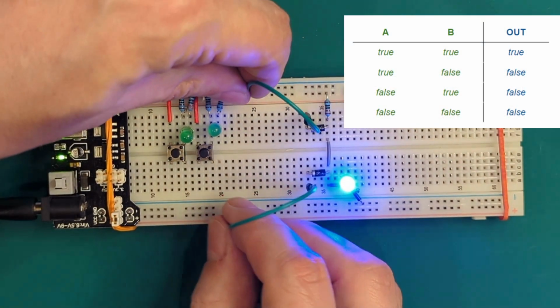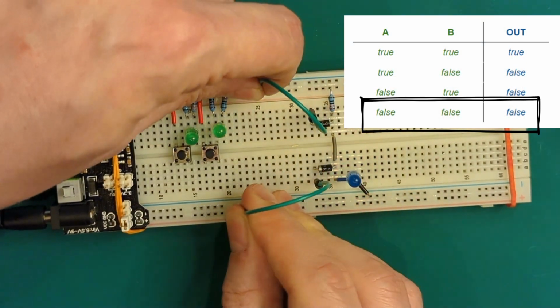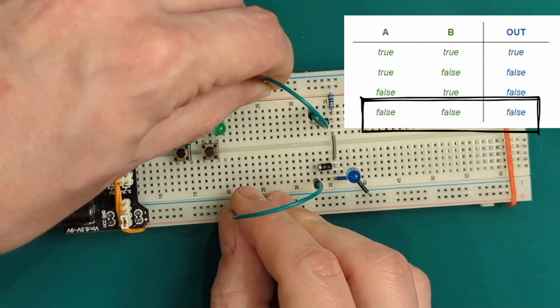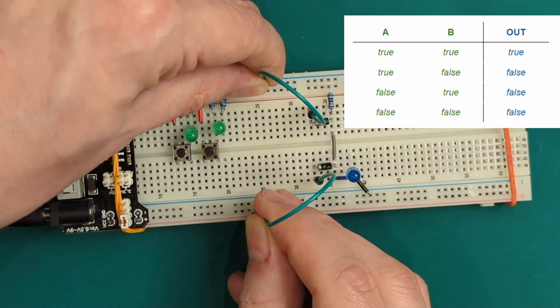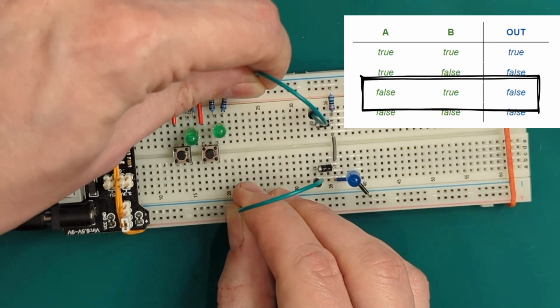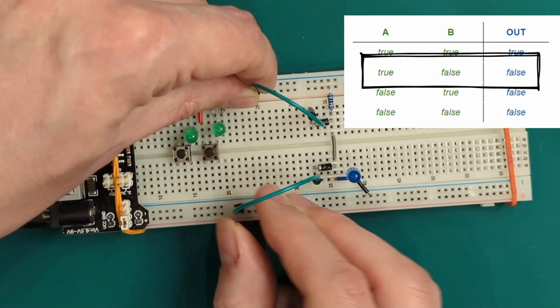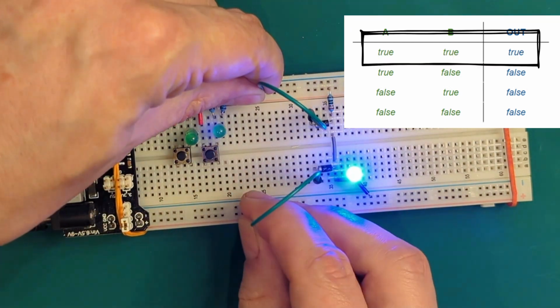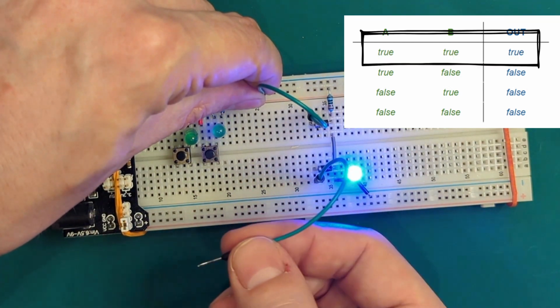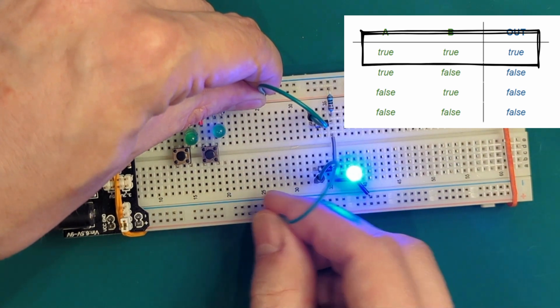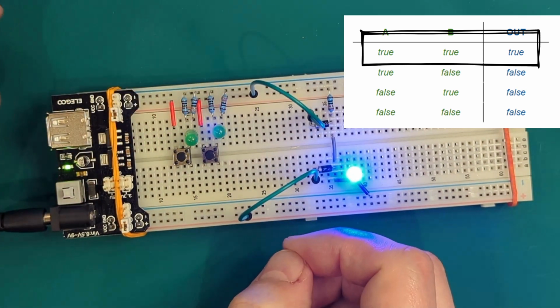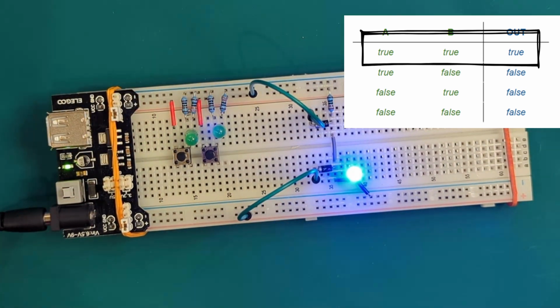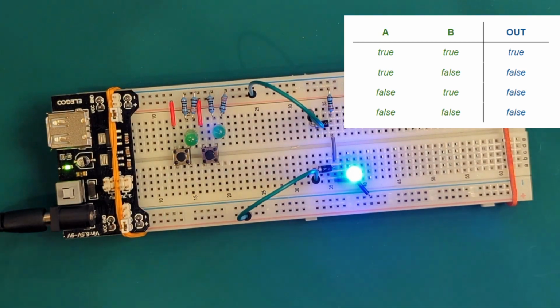Let's demo this. So both inputs are low, and one is low, the other high. One is high, the other low. In all of those cases, the LED is off. But when both are high, and notice that this has this weird behavior when this is floating, but it doesn't matter. When both are high, I get the result I wanted. The output is high. There it is. This behaves like the AND function. That was our rule number one.